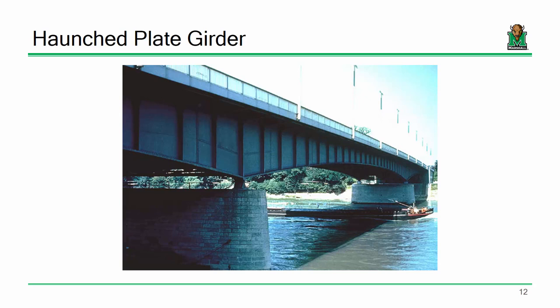And we can see examples of that around here as well. Go to Charleston, or right there near Nitro and St. Albans, and look at those massive trusses that cross the Kanawha River. Just take a look at them, and you'll notice the trusses sort of point up like that. I know some of the folks in the area, have y'all seen that? Well, why do we have that massive depth right at the pier? It's because that's where the largest moments are.